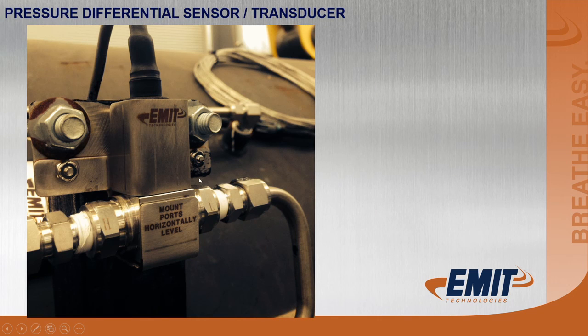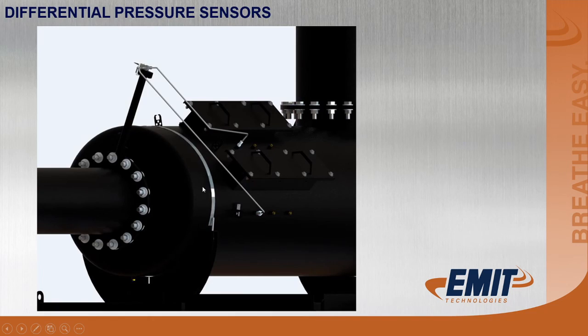Okay, one of the features we want to have on there is a way to measure the back pressure. You can do this manually by a drop tube ahead or behind the catalyst, or you can use a pressure transducer to measure the differential across the catalyst element. Here's a model of the way we'd like to see the tubing on. This is kind of extreme, but it gets the point across that you always want the moisture running away from the pressure transducer if you're going to do that.